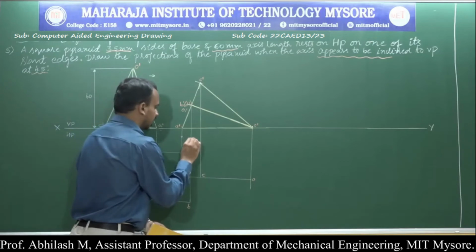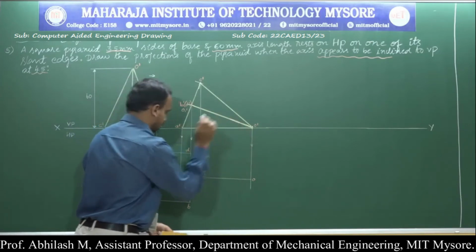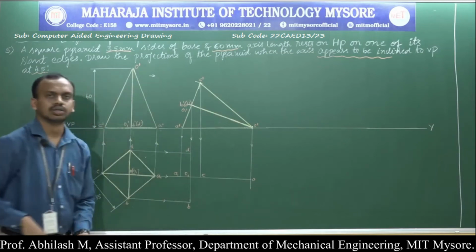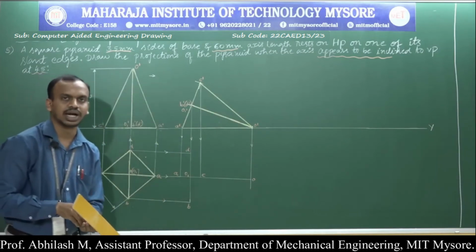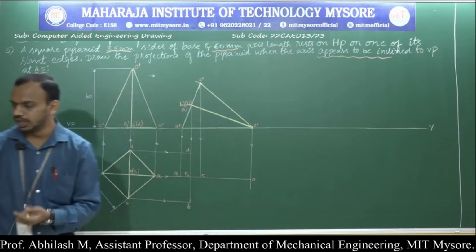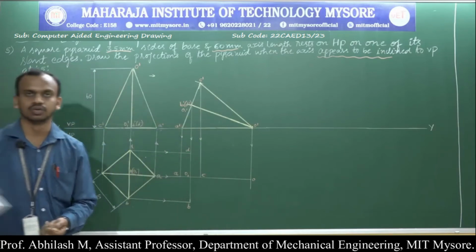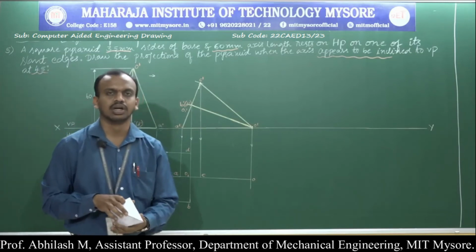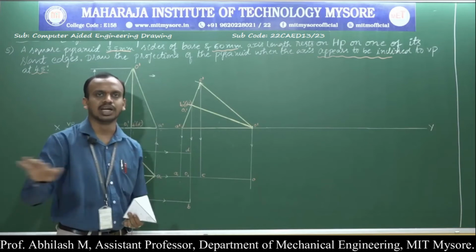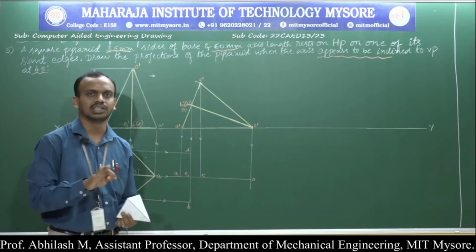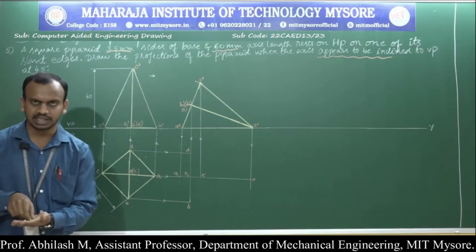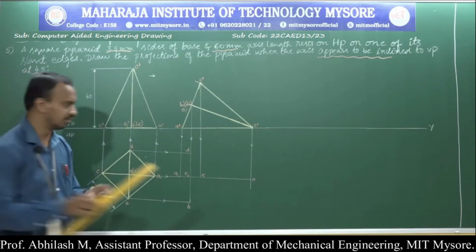Here are the projection lines, and from here also we have projected the lines. So now I am supposed to complete the second position. How to do that? We know certain rules in order to do that particular position, is it not? What is the first rule? The outer edges or the faces are completely visible. So based on that, let us complete that first condition itself.